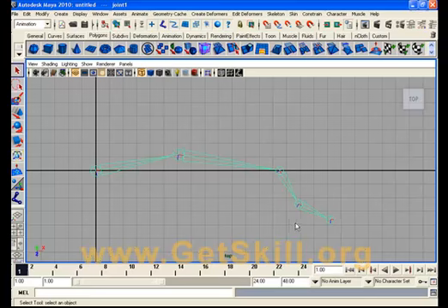At this point you need to correct the proportions between bones and joints. Simply click any joint with MMB. MMB means middle mouse button. First of all, click the wrist joint. Click with left click and then click and drag MMB.